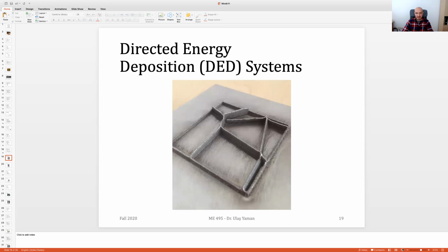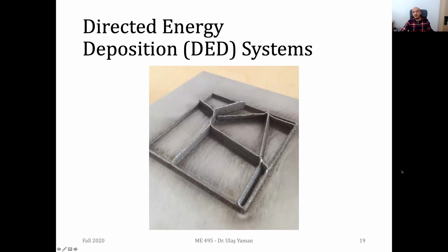Okay, I would like to show you this picture. This is actually the one I have in my hand, and you see that we have height differences. If you look at here, this is the height we have, but here the height is much higher. If you remember on Tuesday, I said that this process is not actually proper for building some single thin edges, thin walls. It's not an appropriate process. With this process, it's better we do some, let's say, repairing task, or we print a solid interior. Otherwise, you will have difficulties.